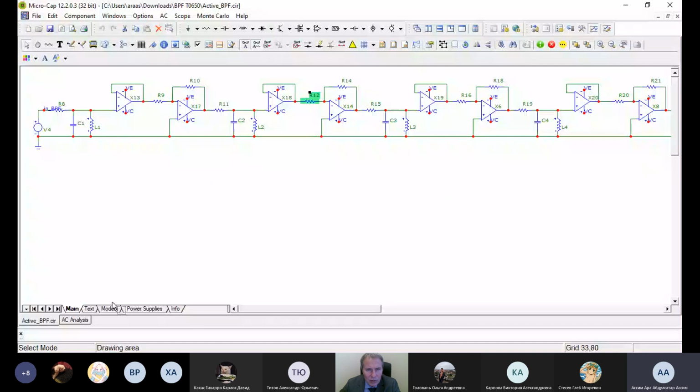There is one very simple recommendation. It is necessary to delete both of these components, the buffer and the inverter, and to use a non-inverting amplifier here. Do you know this circuit? It's like the same thing, but the plus is here.